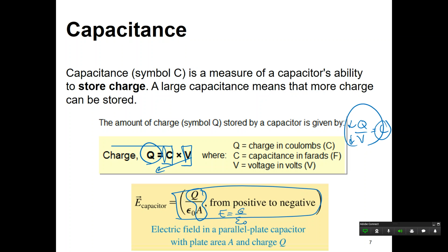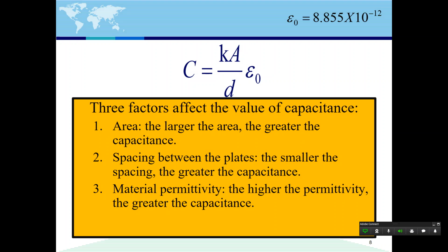But how do you make a better capacitor? So you have a capacitor. Now, how do you want to make it better? Well, then there is this equation here. There are many different things that go into what determines something's capacitance. One is the area of the plates. If I increase the area, I increase the capacitance. If I decrease the distance between the two, then I also increase the capacitance. So if I make my plates much larger and bring them really close together, then my capacitance should go up. Okay, that makes sense.